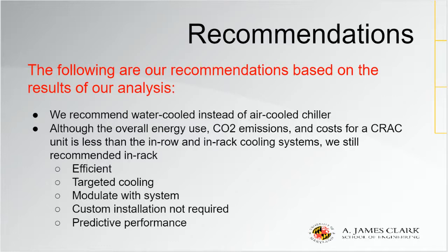Although the overall energy use, CO2 emissions, and cost for a CRAC unit is less than the in-row and in-rack cooling systems, in the end, we still recommend in-rack due to the following reasons. In-rack cooling is in general highly efficient. It allows targeted cooling, meaning it sends cold air to the equipment directly instead of the entire room. As racks get moved around the data center or the equipment is used more or less at a certain time period, the in-rack cooling system will modulate along with these changes. Also, custom installation is not required, meaning specific room geometries and constraints do not play a big factor. And finally, performance of an in-rack system can be easily predicted.